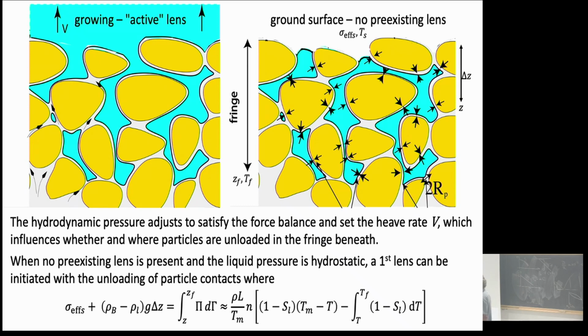So it depends upon temperature and the temperature gradient down here. So there will be times, depending on what we do with the loading conditions up at the surface, and what the constitutive behavior is that goes into this liquid saturation profile, that is the constitutive behavior of the soils, there will be times when we can just freeze ice in the pore space and we never develop lenses. And then there will be other conditions in which we can develop lenses.